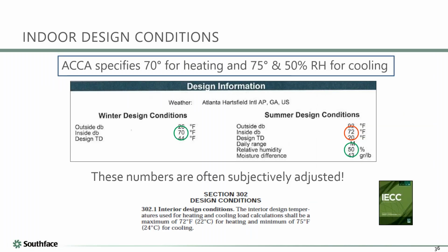The other thing is, don't mess with the indoor design temperatures. You should just use 70 and 75. I've seen people, like in this case, try to slip something in. They made the indoor design temperature 72 degrees, so they would have a 20-degree delta across it. And that's not something you're supposed to do.